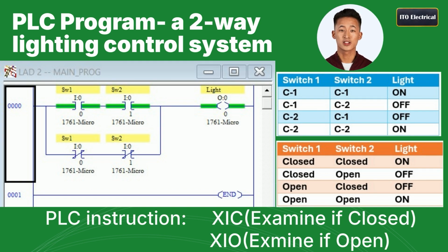You may have noticed that I only programmed the 2 light on switching conditions and not the other 2 light off switching conditions. The reason is simple. We don't need to program the light off conditions. It's similar to setting up an alarm. When you set up when the alarm is on, you don't need to specify when it's off during non-alarming times. So if the switching does not meet the light on conditions, the PLC won't turn on the light. Now, the PLC program for 2-way switching is completed.